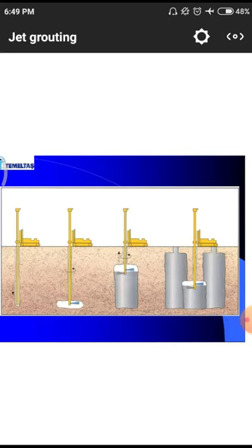After the loosening of material, the total quantity of material will be removed from the particular hole or diameter. After a period of time, the total hole will be filled with grouting material under high pressure. Due to the high pressure and filling capabilities, the total material will settle in a short span of time without any voids.